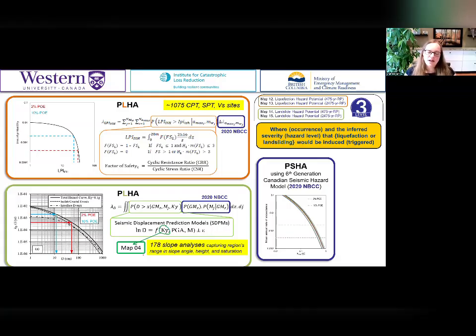And those are coming from embedded landslide prediction or sliding displacement prediction equations and liquefaction potential index prediction equations. It's like we replace the GMM for shaking with the equivalent for liquefaction and landslide. And so in the end, we come up with liquefaction and landslide hazard curves.